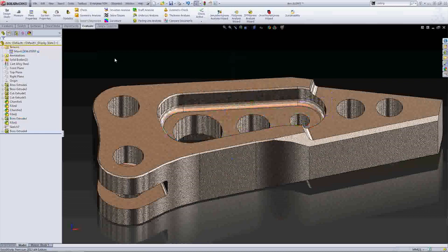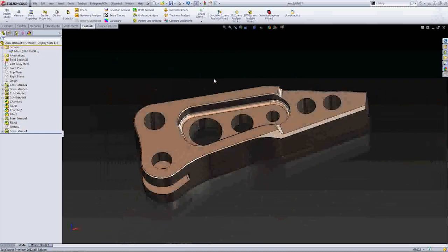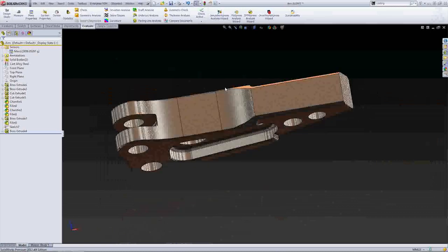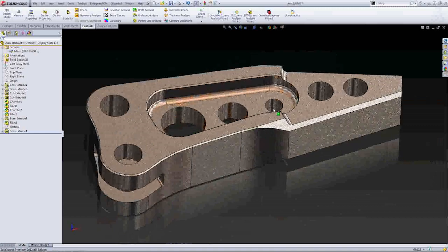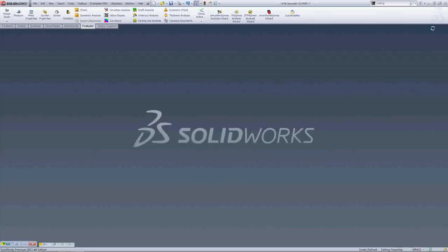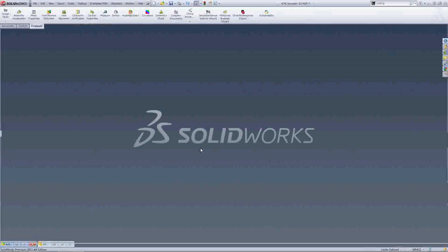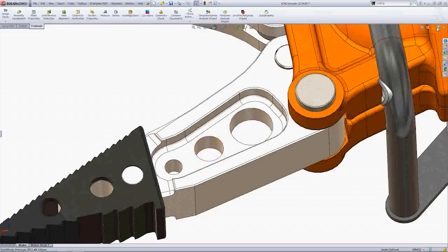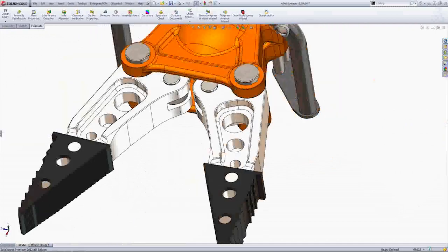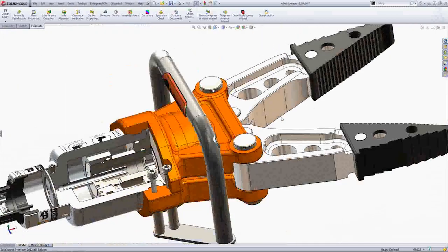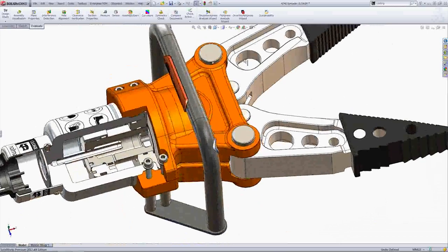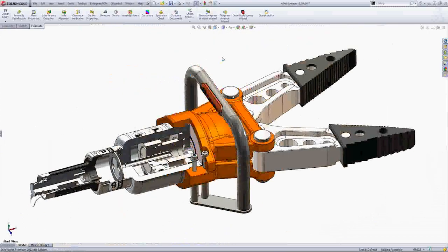I can simply push it down a little bit more and we can see that the mass sensor is now OK. So I went ahead and I made the part stronger, adding more material, but I still kept it within my design constraints, or under 4,000 grams. This is a really neat tool, and adding sensors to help you design in SolidWorks is really useful and a great way to make your designs that much better and using all the power and functionality that SolidWorks has to offer.